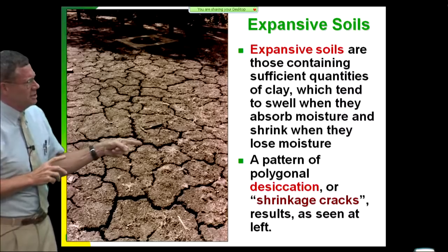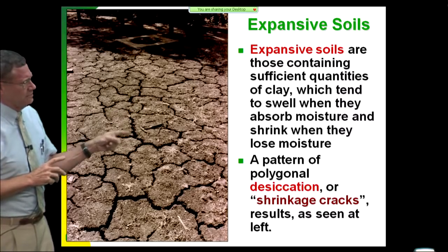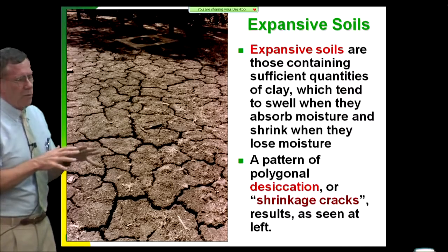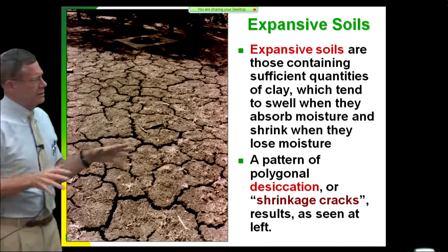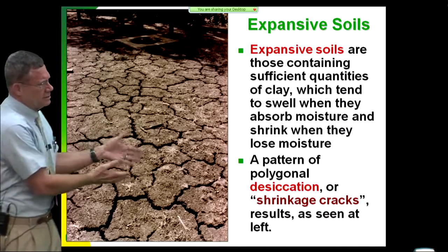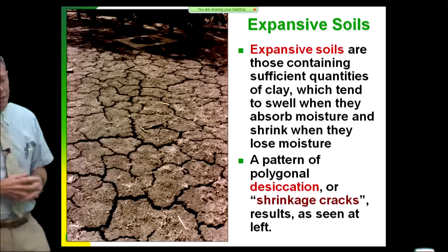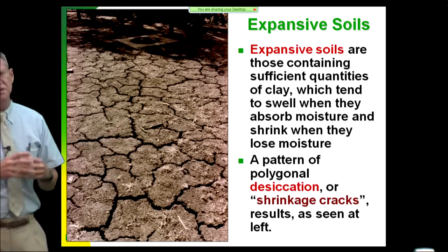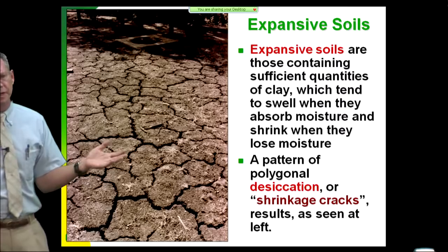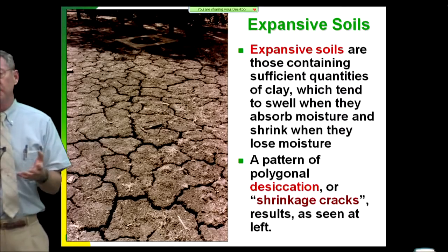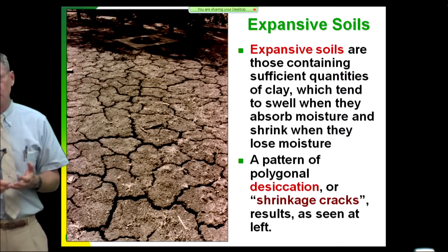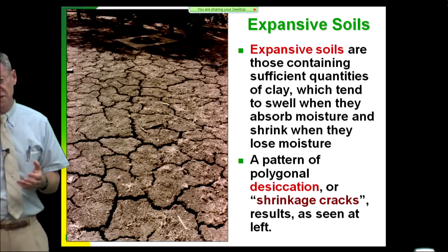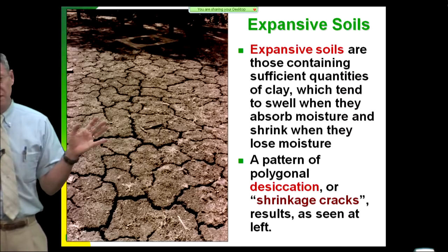But the desiccation cracks are going to be a function of how severe the drying cycle is and what the plasticity of the clay component is. Now, there are very few places where you're going to get pure clay. Most of the sediment on floodplains is silts, but a little bit of clay is going to control behavior. If you have 1% smectite clay, that controls behavior.